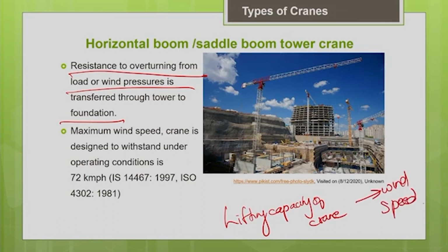Generally, when the manufacturer gives the load rating for a particular crane, he assumes certain conditions. For example, for the mobile crane, he assumes that the surface is level. If it is tire mounted, he will assume that you are going to use the outriggers in completely extended form, and the surface is going to be level and the air is going to be calm. Assuming these conditions only, he would have given the actual rating of the crane. But if in your project site the conditions are different from these ideal conditions, then you have to reduce the lifting capacity accordingly.